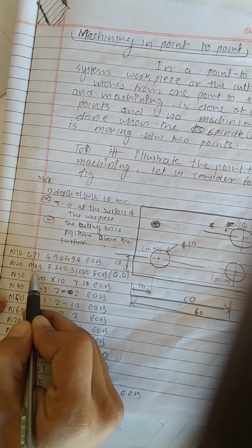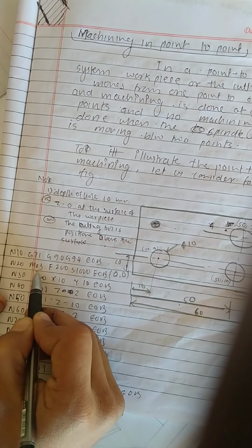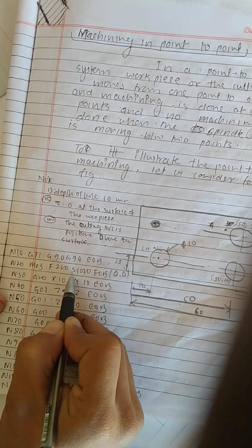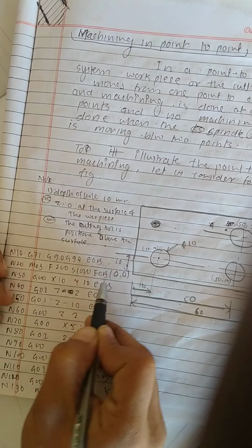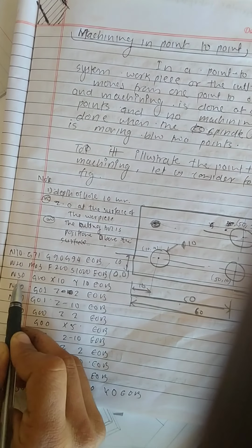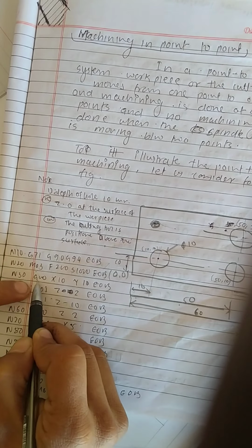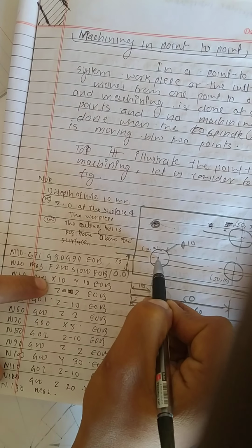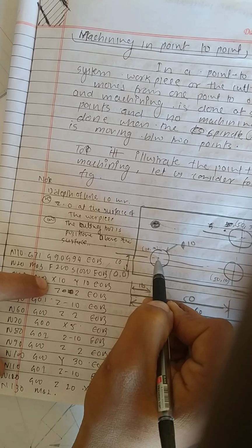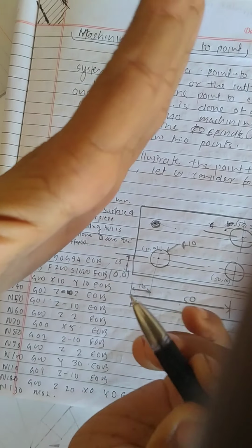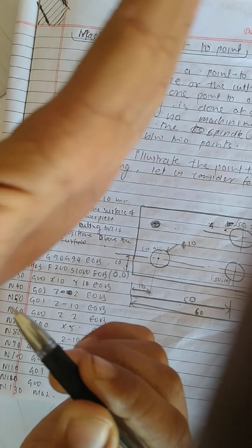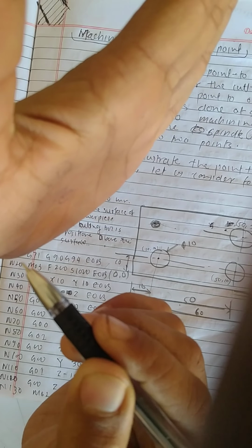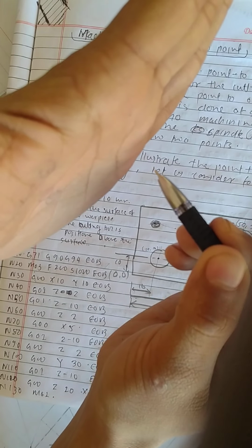In the second block, we will provide miscellaneous codes: spindle start, F200 feed rate 200, spindle speed 1000 revolutions per minute, end of block. And then G00 rapid transfer to X0 Y0. We already assume that my surface is at this distance in the Z direction, and then the tool goes to X0 Y0 this way.